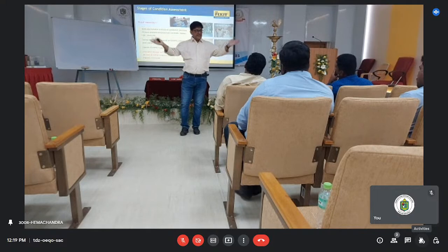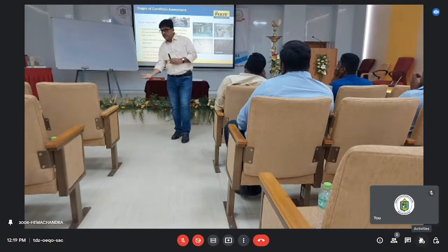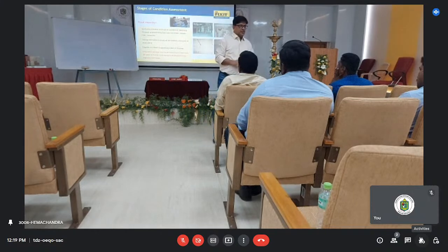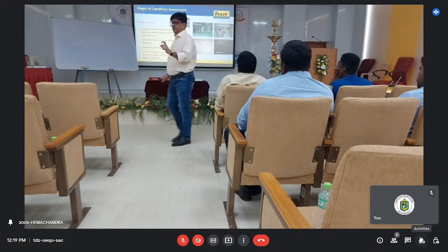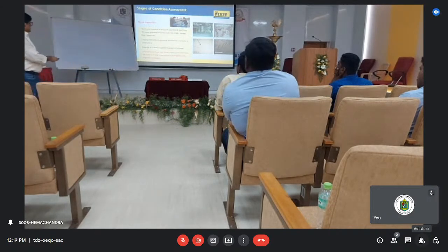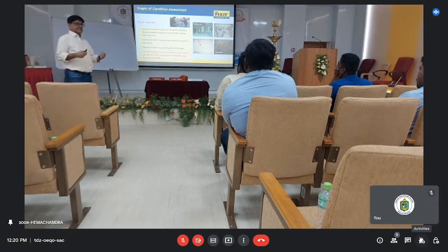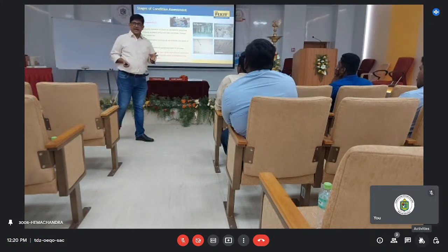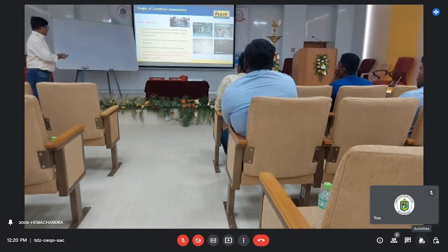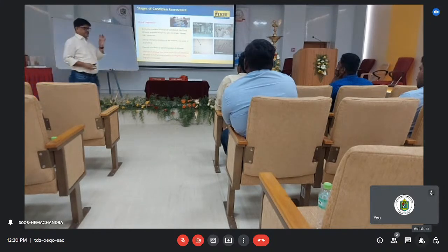If it is throughout the year, that means there is a problem that keeps coming. If it is only in the rainy season, that means only when the water table goes up is the water coming. So we have to get an understanding from the people of when it is happening. The second thing is the extent of distress. How much distress has happened? What problems have happened? All these things you have to see visually.